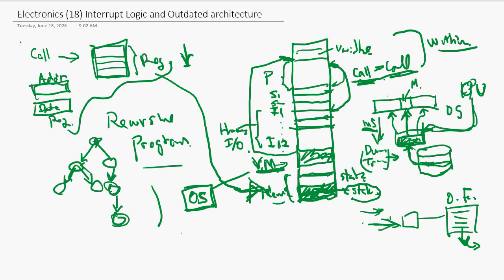Okay, so this interrupt and call work pretty much the same way. You create a stack, and the stack saves all the content in the register, so you can run a fresh new program, and when you finish, it comes back, restores from the stack to the registers and goes back to the original program and continues whatever work you are doing. Now in this process, how do you save all the content to the bottom of the memory?